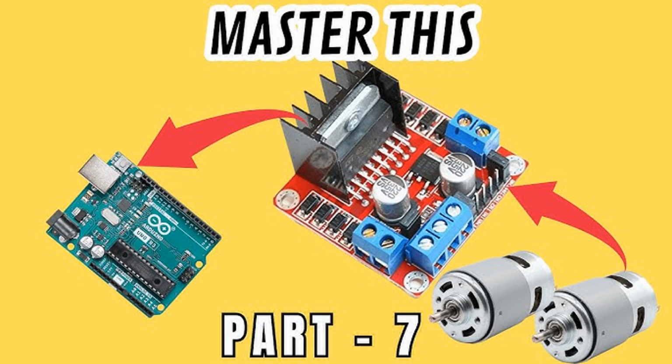Applications: Useful in applications requiring variable speed control, such as drones, RC vehicles, and electric fans. Examples: PWM control is often integrated into other motor drivers like H-bridge ICs or MOSFET drivers. 3. MOSFET-based drivers. Function: MOSFET-based drivers are used to drive high-power DC motors where higher current handling is necessary.